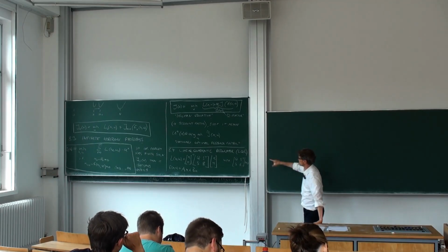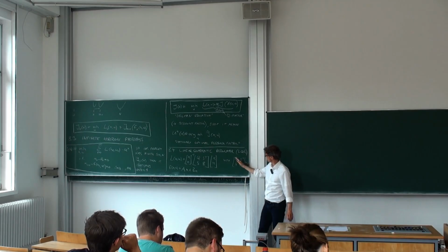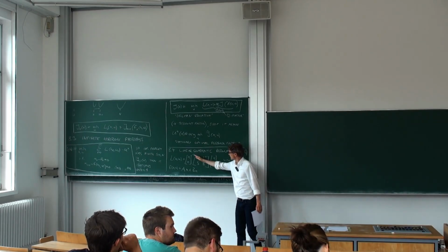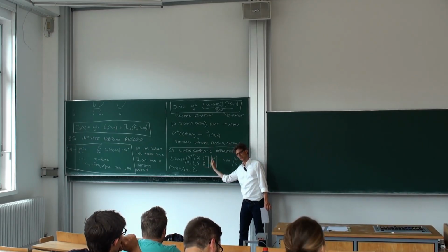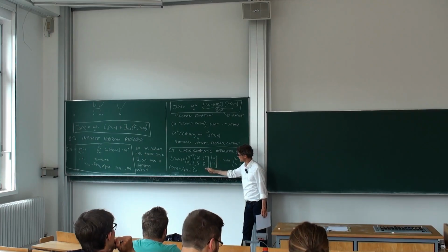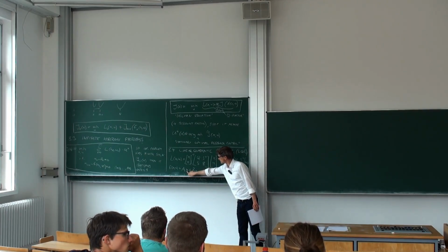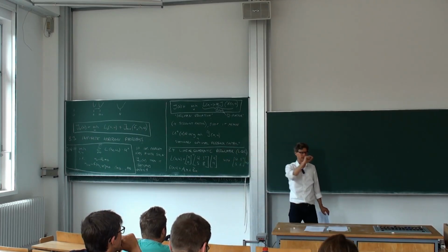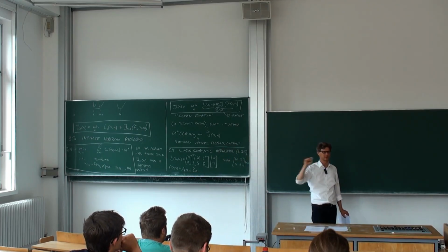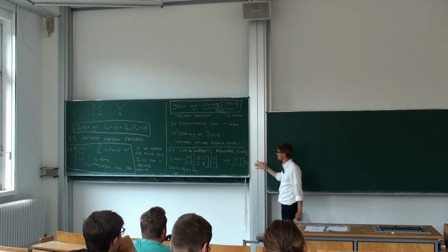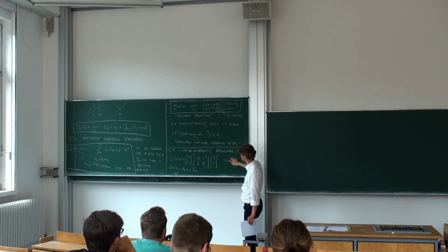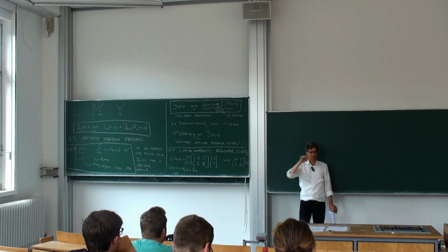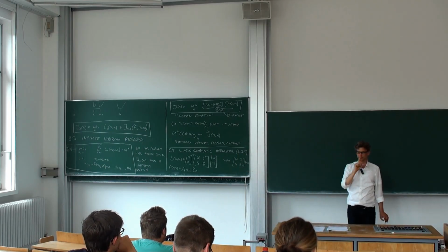If this is a positive definite matrix, then at zero the cost is zero, and at every non-zero point it's not zero. You will stay at the zero state with zero control. So zero is a perfect value where you could stay infinitely long without incurring any cost. So we see that this infinite horizon problem with that cost function actually leads to a finite cost.